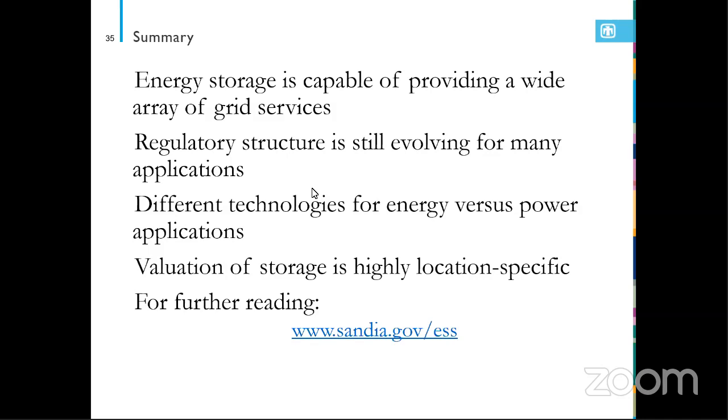Yeah, from the perspective of Opalco, the utility we'll be working with, flow batteries are potentially a workhorse in the sense that you can cycle them quite frequently without much or any degradation, and they can have a very long economic life of 13 to 20 years. Whereas if you're using lithium ion for that purpose, you would reduce its economic life to well under 10 years potentially. But lithium ion battery systems are more cost effective.